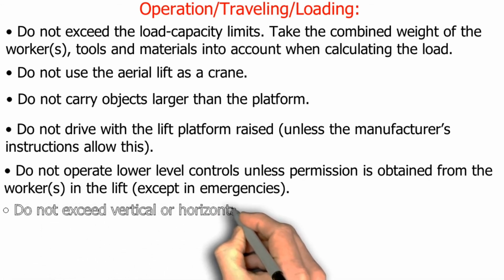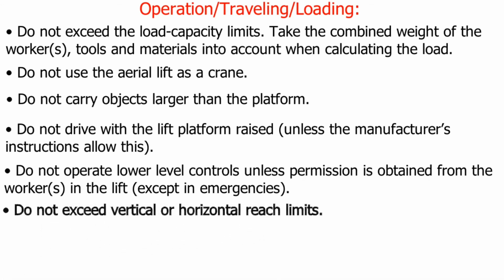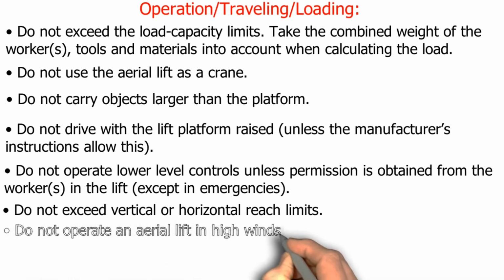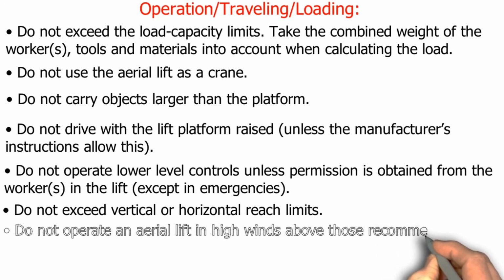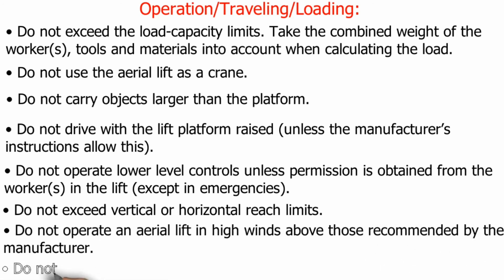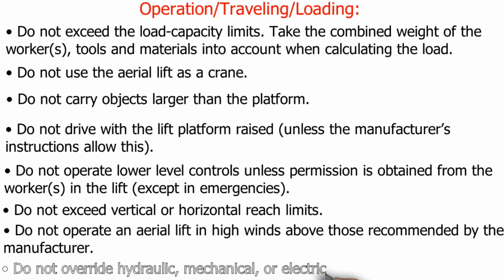Do not exceed vertical or horizontal reach limits. Do not operate an aerial lift in high winds above those recommended by the manufacturer. Do not override hydraulic, mechanical, or electrical safety devices.